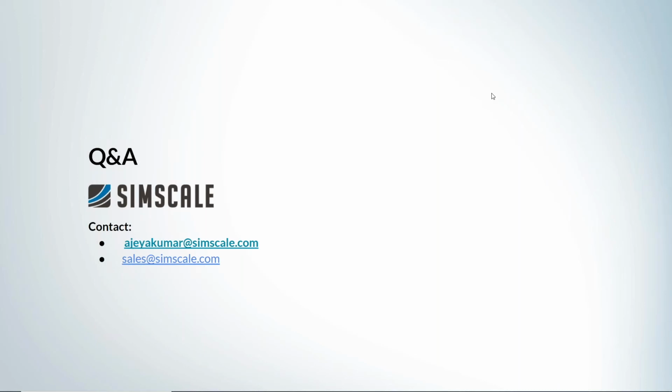But what we actually recommend is that when you have the CAD model inside SimScale, you have the entire autonomous meshing that can work perfectly. And you also have the option to edit your CAD within SimScale. When you have your CAD model in, you can simply increase the surface area of the radiators or even delete or add new bodies to the geometry and then start simulating other scenarios. So it is preferred that you bring in the CAD model, but you still have the possibility to load your own mesh also. Okay, great.